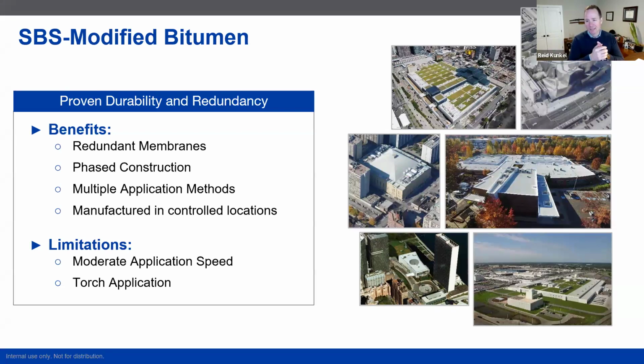Torching is a growing concern for building owners and consultants in certain geographies and certain building types or construction types, and so it is something to always keep in mind when a flameless application is called for. Typically, SBS is put down with a torch.